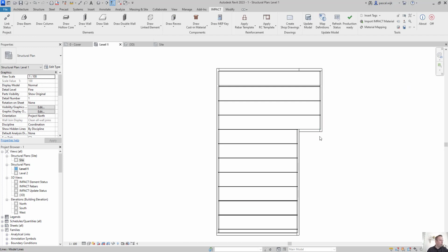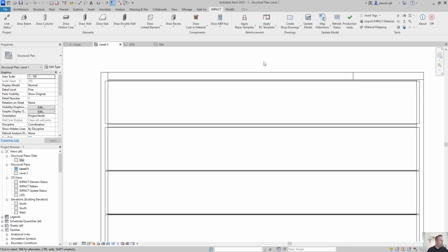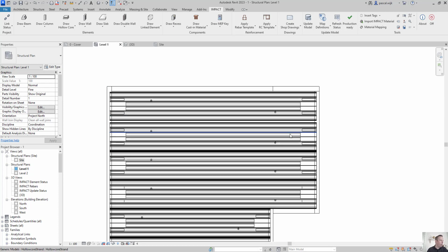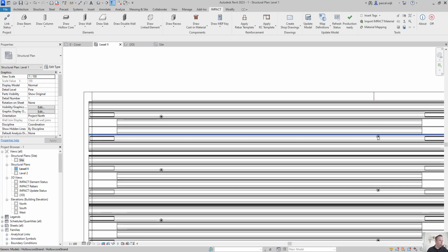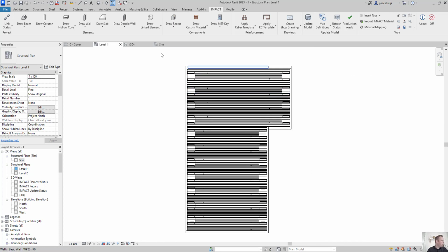Alright then, so now I've got my hollow cores here, and let's see what I've done here. What we can do is just go to wireframe, and here you can see that I've got my solid cores there and my connection recesses, 2 at each end, and I also automatically got my lifters there. So there's not that much to do anymore.